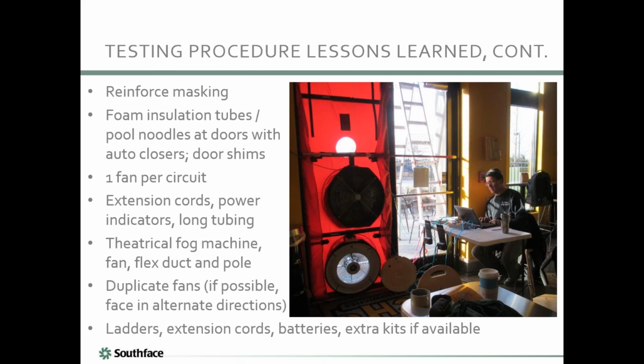Just some little details. It's good to have some long tubing. Tubing can be a little adventure. You don't want to get it wet. If water gets in the tubing, it has a little capillary effect that can give you garbage readings. And the ends can get frayed. And what happened many times when we had a lot of people doing a blower door test, with lots of tubing, is that inevitably somebody steps on a tube. And it sends a pressure spike, turns your fan off, and the software gets confused and shuts off the test. So it's important not to step on the tubes. Ask me how many times we've learned that lesson.